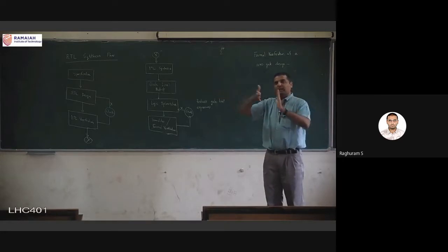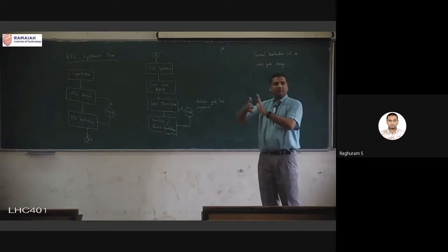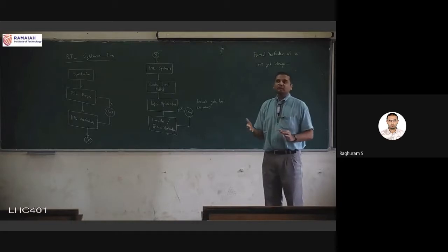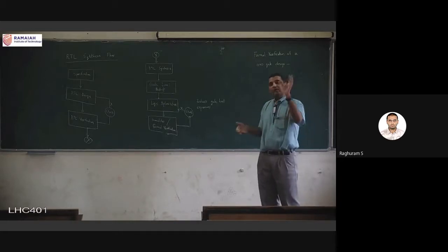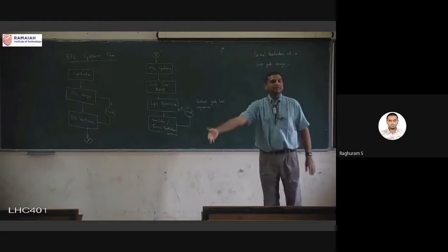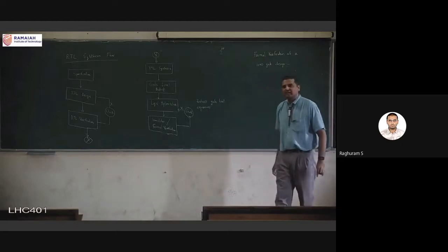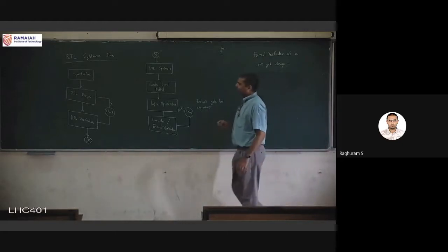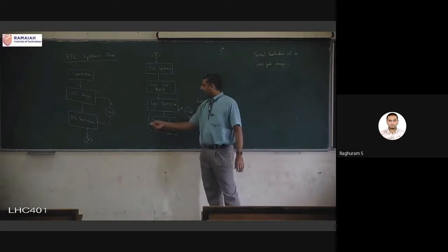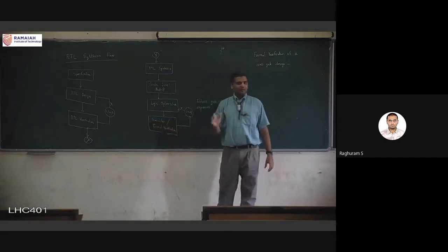And when you look at the internals of the circuit, maybe not all these 2 power 64 are coming in the same order, they might get transformed. So the question comes, what about the order? If after this input I give this input, will the circuit malfunction? Questions like these are very difficult to answer with simulation. Generally, they won't cause a problem.